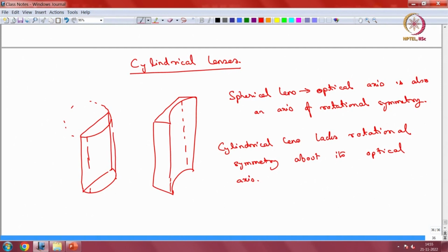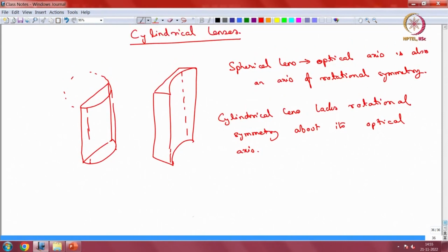Whereas a spherical lens will produce a point focus for a point object, a cylindrical lens produces a line for a point object. So, the image of a point object in the case of cylindrical lenses is a line. Now, you might want to ask why this is, how is this helpful? We will see that in PIV, particle image velocimetry, this property of cylindrical lenses to stretch out a point into a line becomes extremely useful, and we are going to use that for lighting in our case.